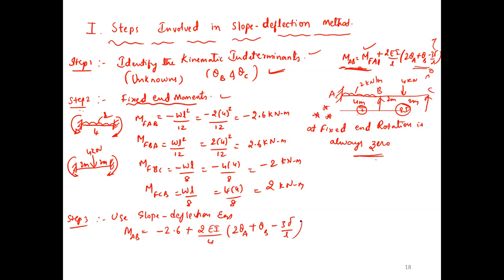In this problem I have not given any sinking. If sinking is not given, this term becomes 0. Here theta A is also 0 because support A is fixed.